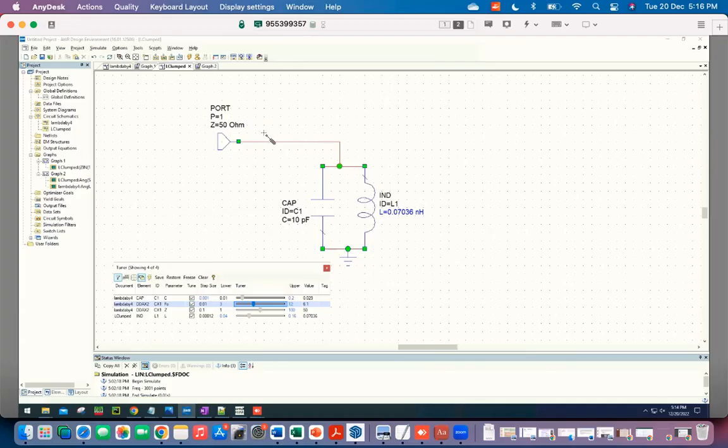So what is happening now is that this resonator is dissipating through a resistor which is now being modified by the presence of the series capacitor. So if you have a small capacitor in series with a resistor, then it will appear as a much bigger resistor in parallel. So R goes up, Q goes up. So that's the alternate picture one uses for this.